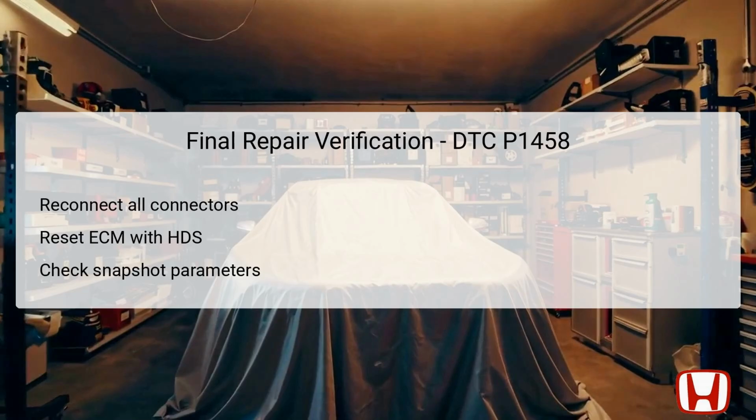Subsequently, utilize the HDS to reset the Engine Control Module, ECM, which clears any existing DTCs and prepares it for fresh data. Execute the ECM idle learn procedure to ensure optimal engine function post-repair. Following this, take another snapshot for approximately 3 minutes without starting the engine to evaluate the FTP sensor parameters once again.